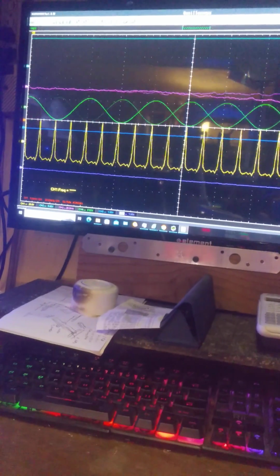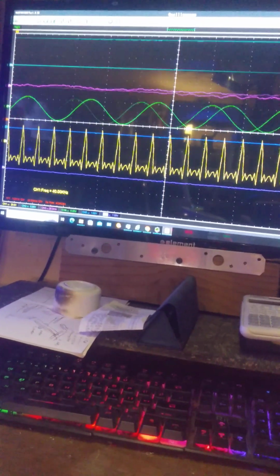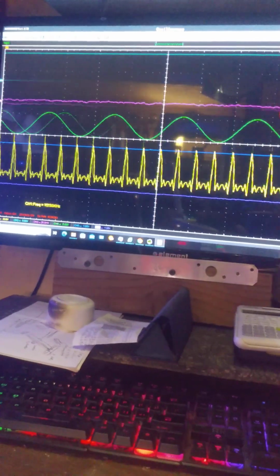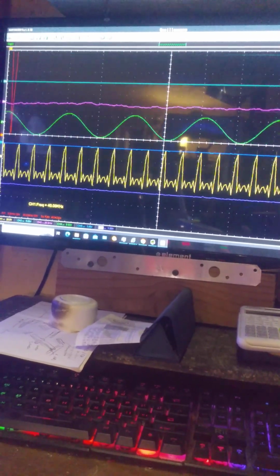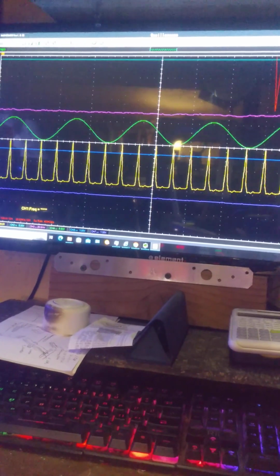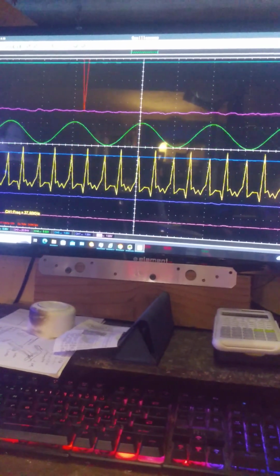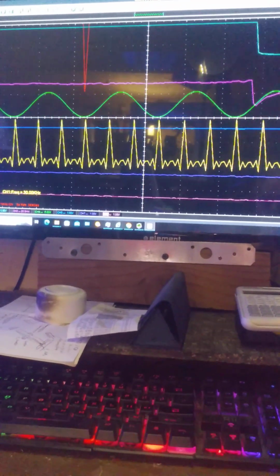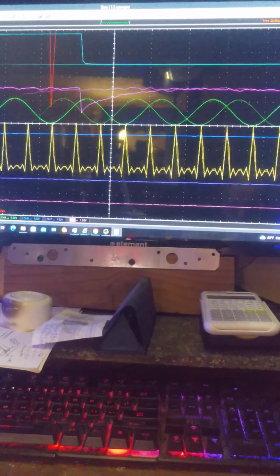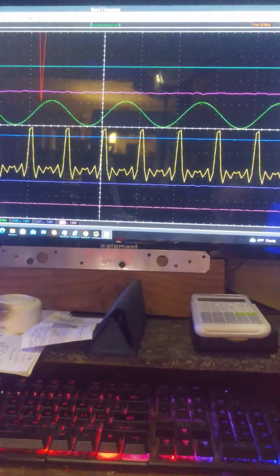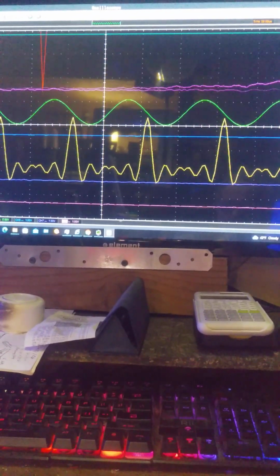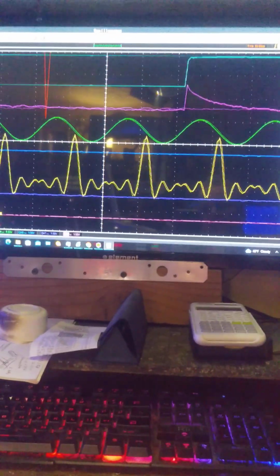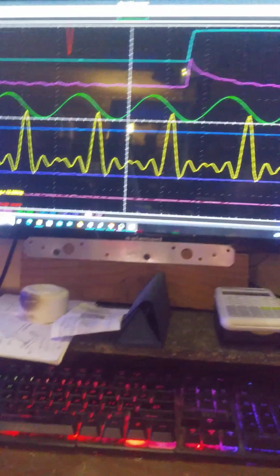See, it's still set at 40 kilohertz, and it's still occasionally saying it's 40 kilohertz, although it's sporadic. And channel 8. But again, it becomes certainly more undefined. Now I'll take it down to 30. And again, it's pretty scraggly. So, take it down to 20, 10. Now 10 is starting to be usable. So if you have all 8 channels, I would say 10 kilohertz at most.